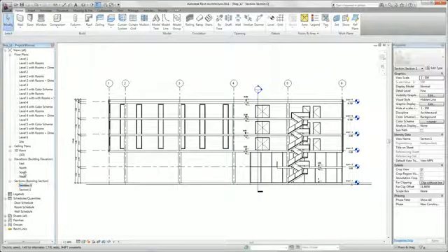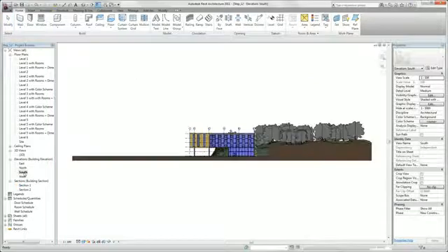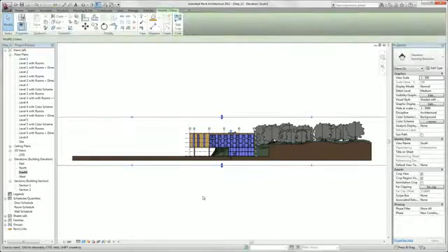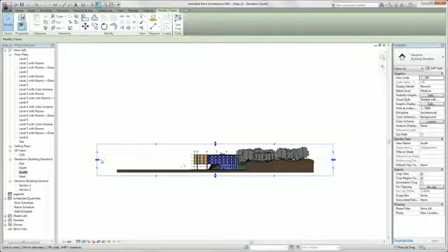Now we switch into the south view. Always remember that in Revit every view has extents which you can modify. This is necessary when you like to place views on your sheets. Select here in the view control bar show crop region. We select our boundaries and with the blue triangles we crop our view.